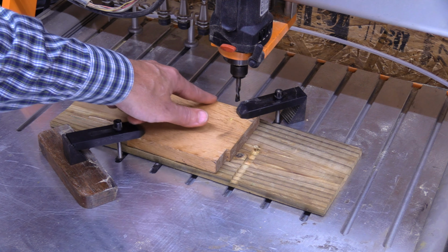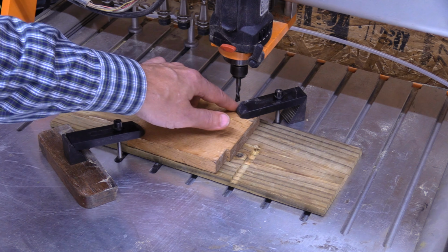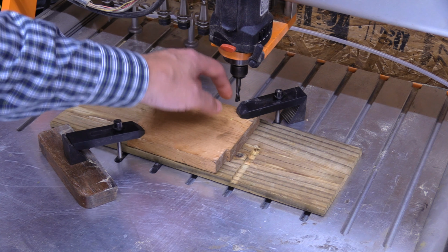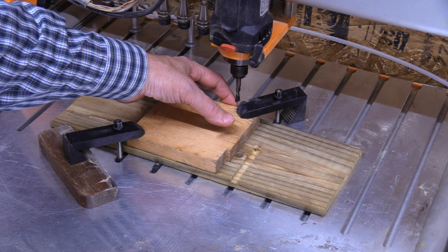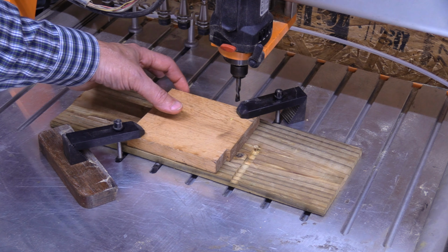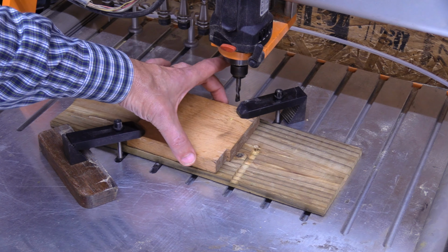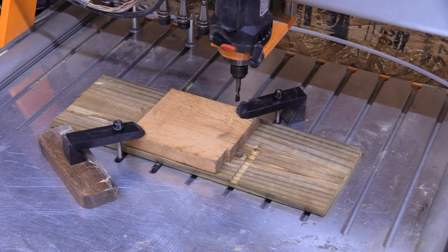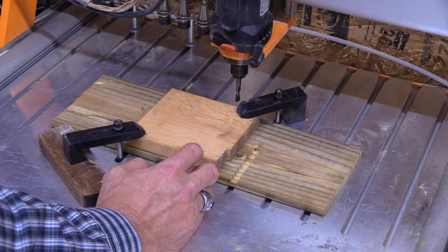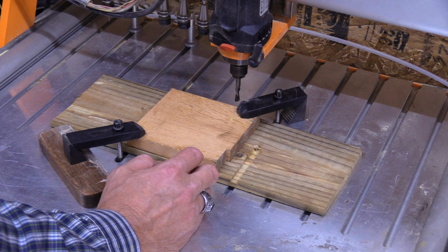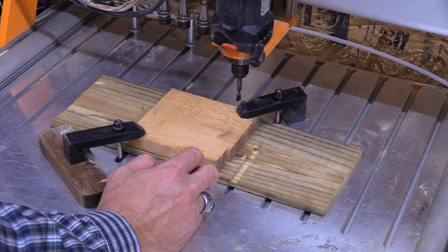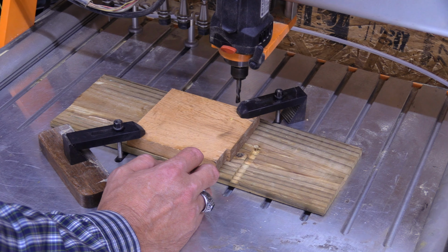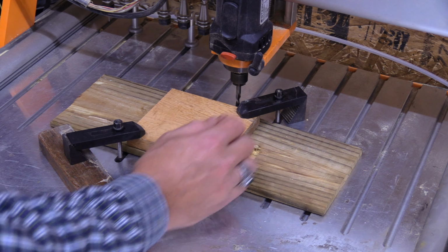The first thing I need to do is, this is a nice flat line in the back here, so I need to make sure that the Y, when I zero this out against the back of this, is the same here as it is here. That way I know that I'm going to be perpendicular to this end, right? I'm just using the jog commands on my machine: left, right, up, and down for X and Y, and Z is page up and page down, right?